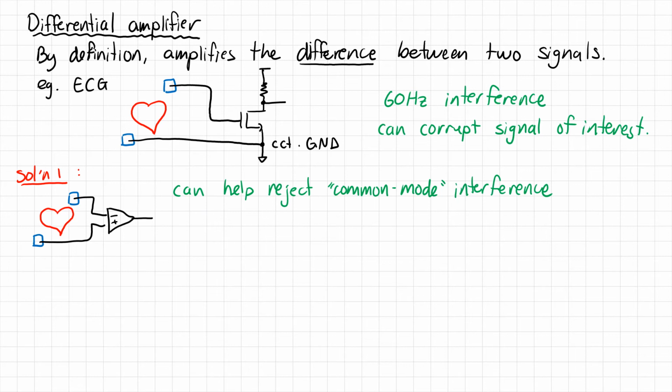Now there are other techniques we can use to cancel some of this common mode interference, but for now, going to a differential architecture is reasonable. The idea here is if you do get common mode interference coupling onto your circuit, then as long as the interference is the same on both the positive and the negative terminal of the amplifier, there will be no potential difference between those terminals, and therefore that common mode interference will not be amplified, ideally.